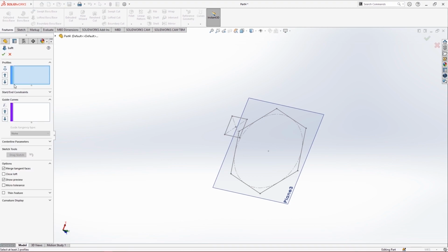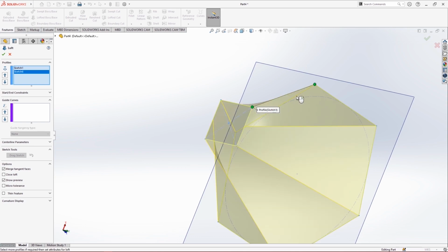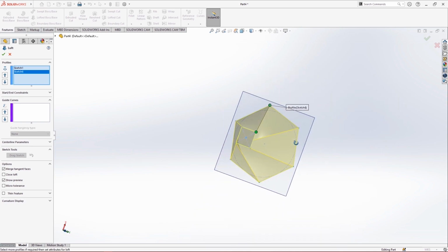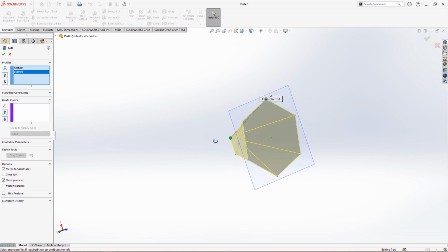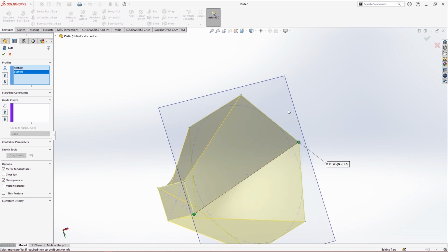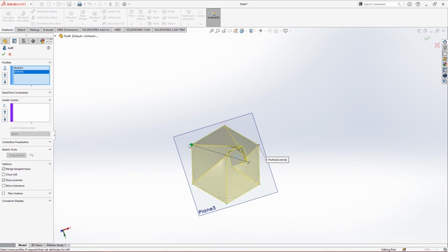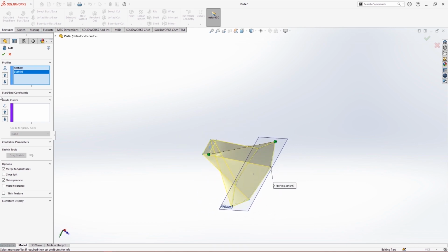So just click here, and you will have to add surfaces here. You can do it easily in multiple steps. For example, you can click on one and select another, and you have a surface. You have the lofted solid, actually it's a solid. So you can mess with these pivot points. You can see the shape changes accordingly, and you can just keep on changing it. So this is how the loft works.